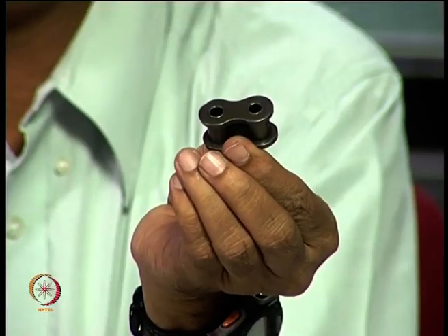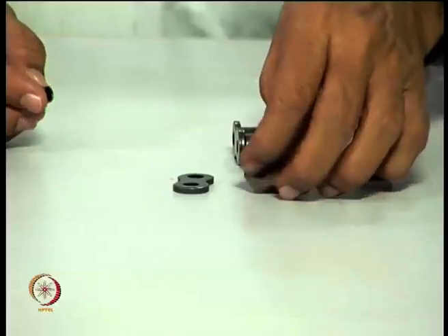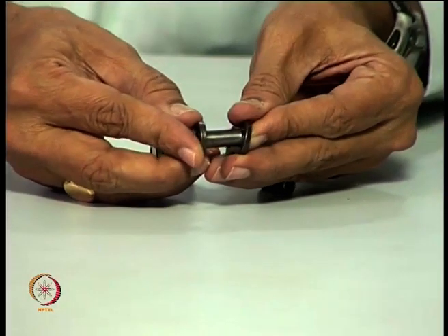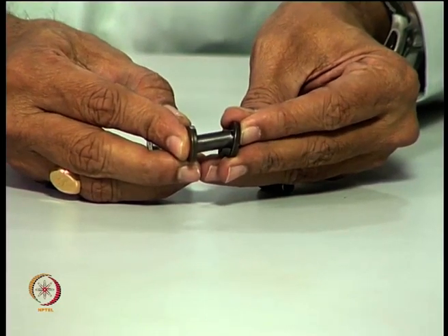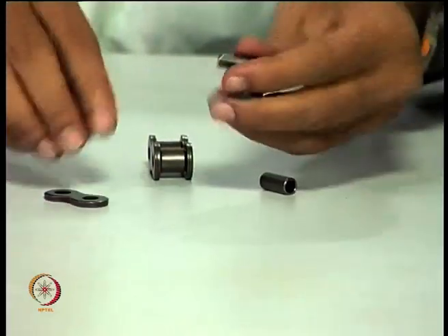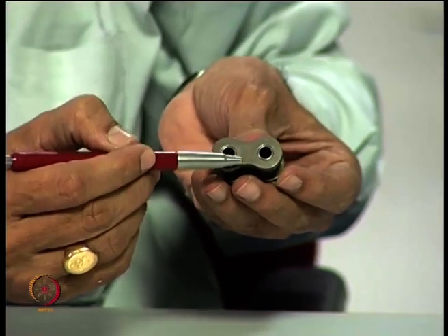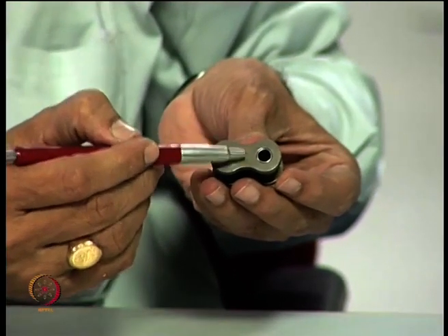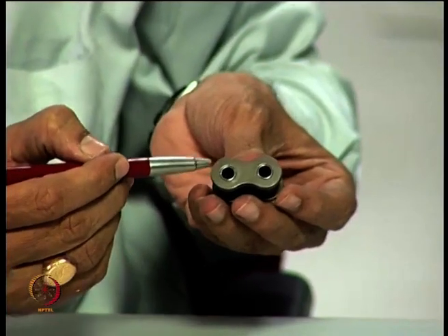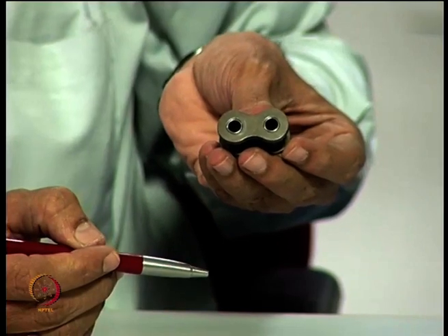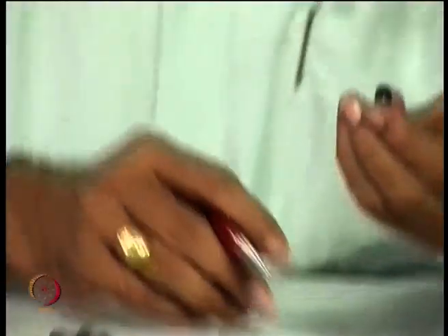See, you have to know how this component is fabricated. Suppose I take a block of material and then I go to CNC machining and then machine out this, that is one thing. And how it is done is you have essentially plates, and these plates are brought together by putting the appropriate bush, and the bush has to stay in place. So, you have an oversized bush and this has to be inserted. So, this is done with an interference fit. So, apparently I do not have any external load on this chain link, but because of the way it is manufactured, you have stresses developed, you have a bush here, you have stresses developed very prominently here, and it is comparable to the service loads. The stresses developed are not small in value, they are comparable to the service load.